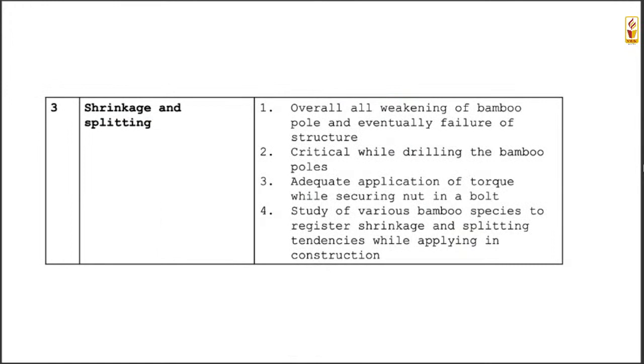There are some other problems based on what species you are using. In case of bamboo, sometimes it would impose where you are using it, because you should realize that bamboo demands a moisture content of around 18%, whereas generally when we are talking about timber, 12% is all right. Which means that if you are using bamboo from one region in another region, the same is true for timber.